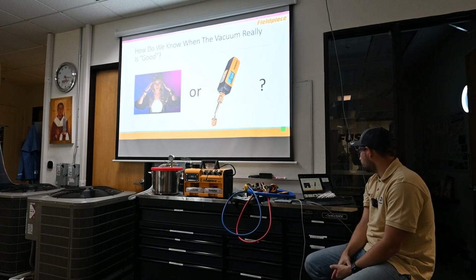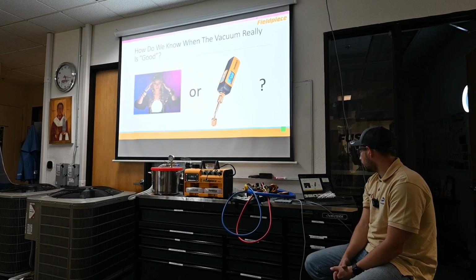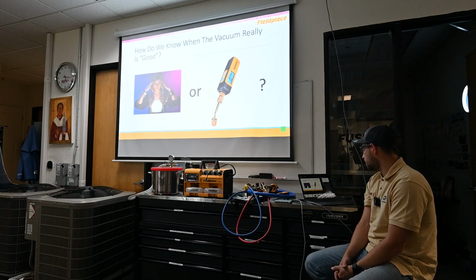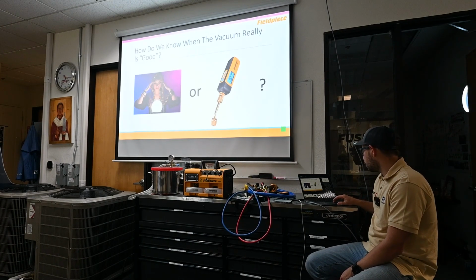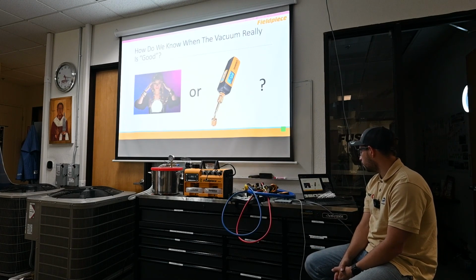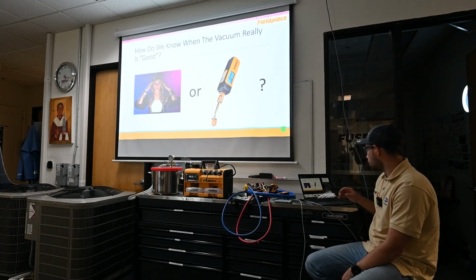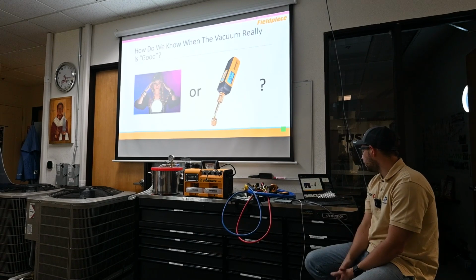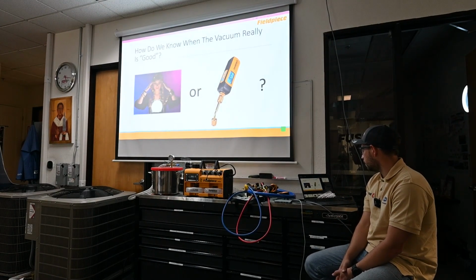Since most technicians are not physicists and cannot see if any non-condensables remain in the systems, they need to use a gauge to measure the pressure in the systems. A maximum pressure value under vacuum is set by the equipment manufacturer of the refrigerant systems. The manufacturer's specified pressure or lower should be achieved in the systems at the time of installation and repair.